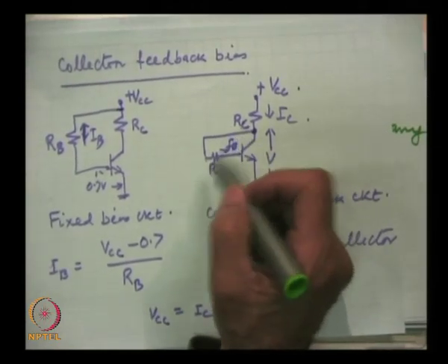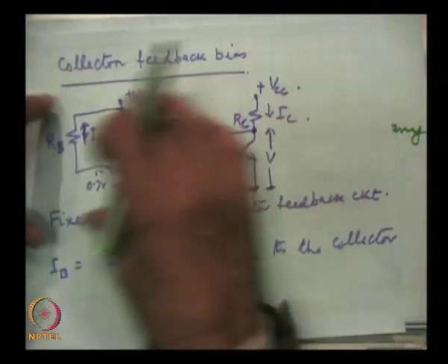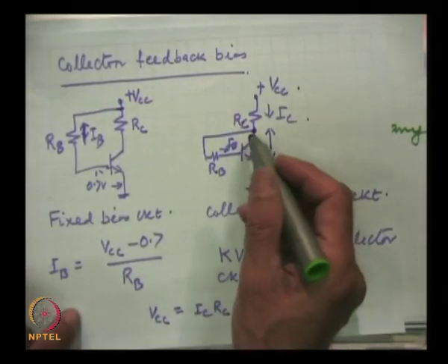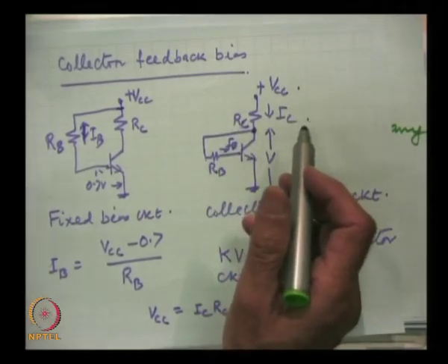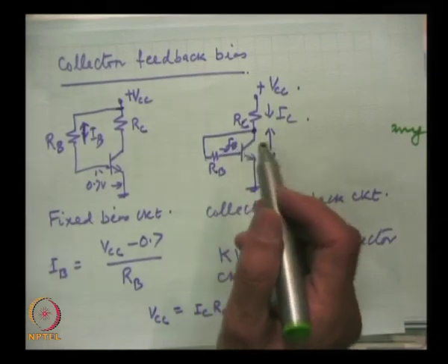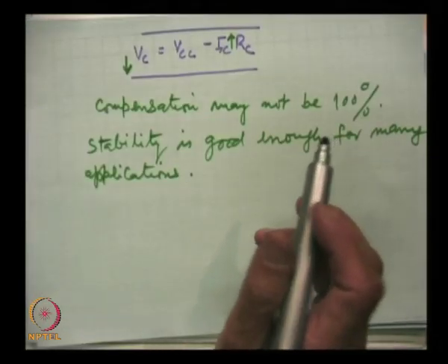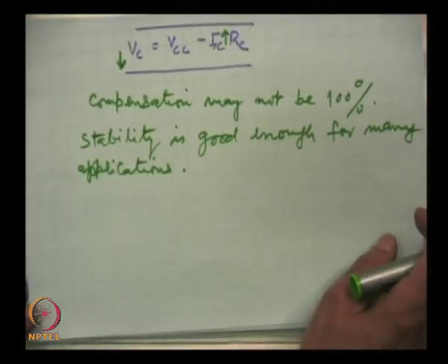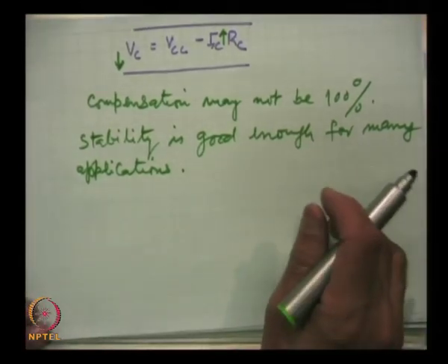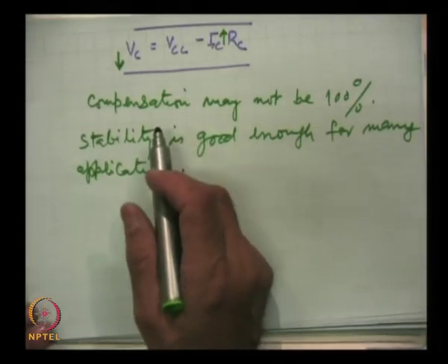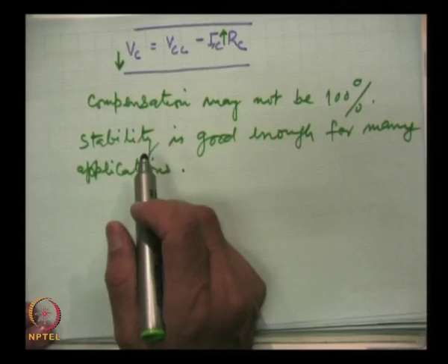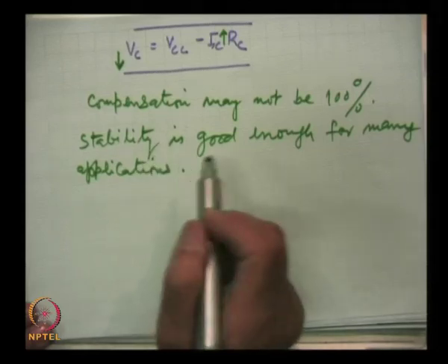So, the number is reduced to half when we talk of a system in which several stages of these circuits are there, then the reduction of resistances is significant to reduce the cost of the circuit. So, that is very important point. Now, if very high stability is not the requirement, which is true for many applications, then this collector feedback bias can be used to achieve the stability.